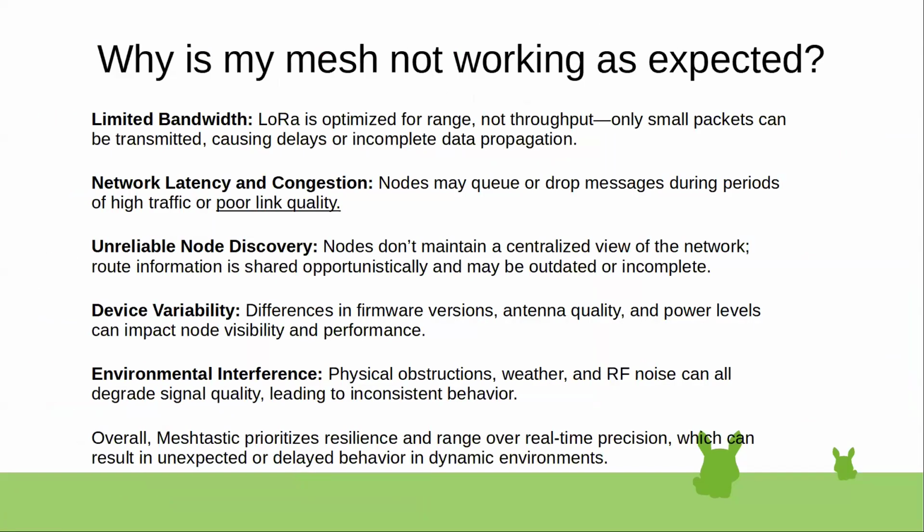So, troubleshooting: why is my mesh not working? If you go online, some people will say, Meshtastic is the stupidest thing ever, it does not work. And that's true if it's not deployed correctly. I think the biggest gotcha with this is it's sending packets, and it doesn't care if they get to the other end, it's just going to send them. So you might ping someone and not get a response, but that person hears your ping.